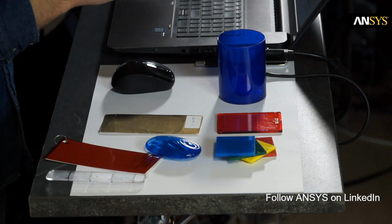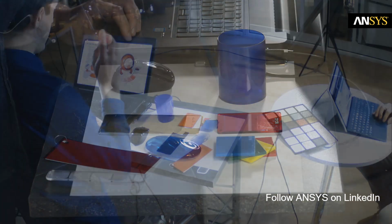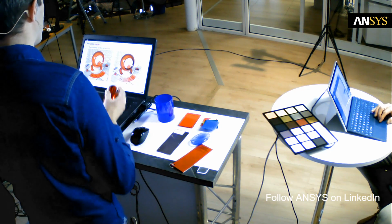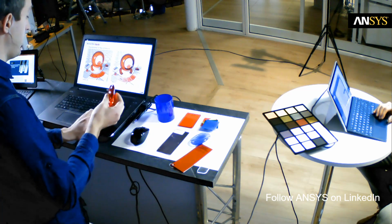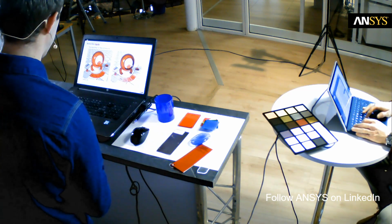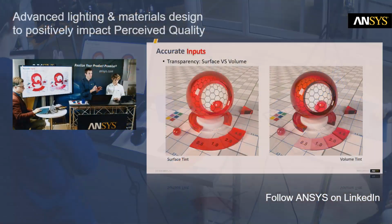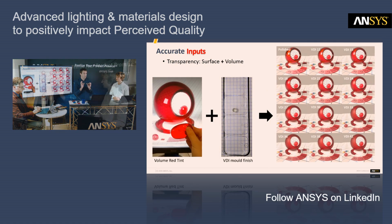The dye is diluted into the wall part, the wall plastic, and here you can see that the color actually depends on the thickness of the material. The geometry is part of the input, and will induce the color depending on the material properties. So that's something we do in Speos. We separate the surface properties from the volume properties, because these are very different behaviors. But the beauty of this is that in Speos we can combine surface and volume properties.